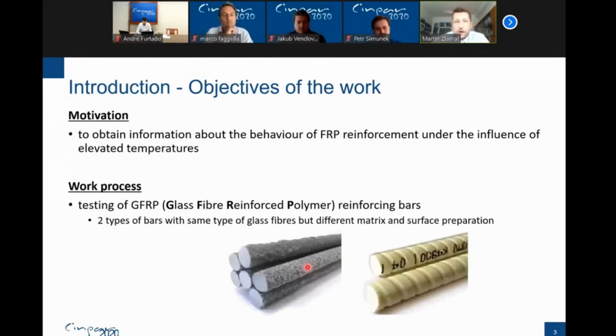So in our experiments, we focused on a behavior of these FRP reinforcing bars under effect of the elevated temperature or under effect of a fire on some structure which is reinforced with the FRP bars. So we want to obtain the information about the behavior during the increasing of the temperature. We start with the first phase last year and this year. So we started testing of GFRP bars, so the bars reinforced with the glass fibers.